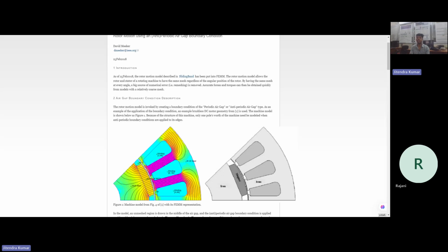Which single phase generator are you trying to design? BPM BOR, brushed permanent magnet outer rotor. So surface magnet. It's like a single phase PMDC only, but it's an outer rotor one. Here, switching is like motor control, but we are using it as a generator. Single phase is not possible, sir. Even in RMxprt it is also not possible.